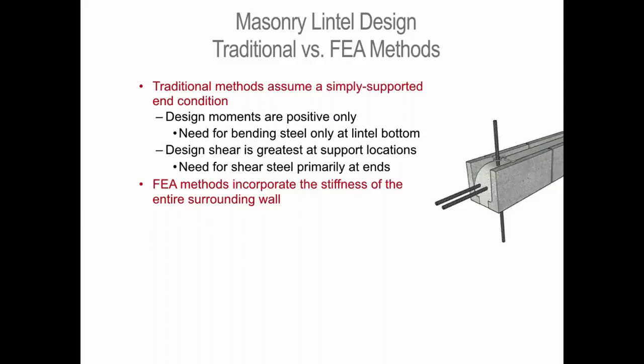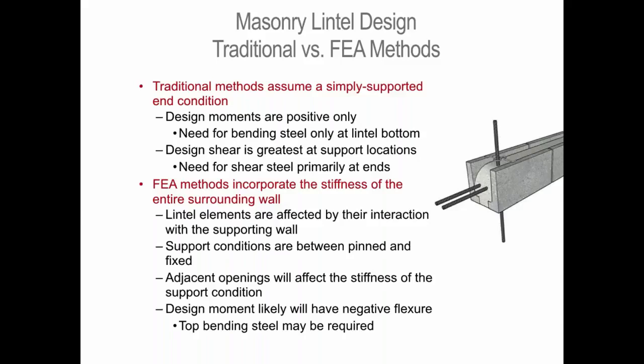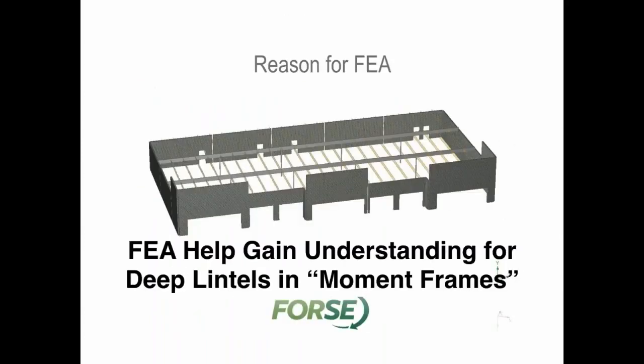Finite element methods really do incorporate the overall stiffness of the wall around it. A lot more words in here, but basically I can have this analysis be a lot more complex with finite element analysis. We have to encourage engineers to use finite element analysis. It's buildings like this. I can use an FEA and I can have an efficient masonry lintel. This is just a single-story building, very long spans, I need to put a piece of steel in there. We could have designed that very efficiently with masonry with some of the principles that we just talked about.